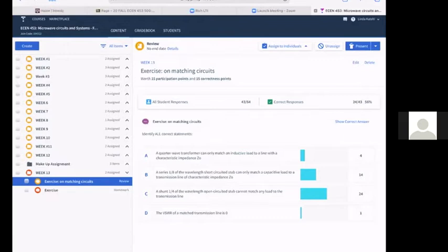Okay. Am I right? Right. Okay. I guess yes. From a lumped element perspective, I guess I was thinking back to when we were designing filters, and it just seemed like a very strong thing. Short, it has to be a series LC in shunt configuration. But even if it's a series LC, when it is 1/4 of a wavelength, an open stub is a short, no matter how you want to see it. It's a short when it is 1/4 of a wavelength. It may not be a short if it's away from that, but at 1/4 of a wavelength it is a short.